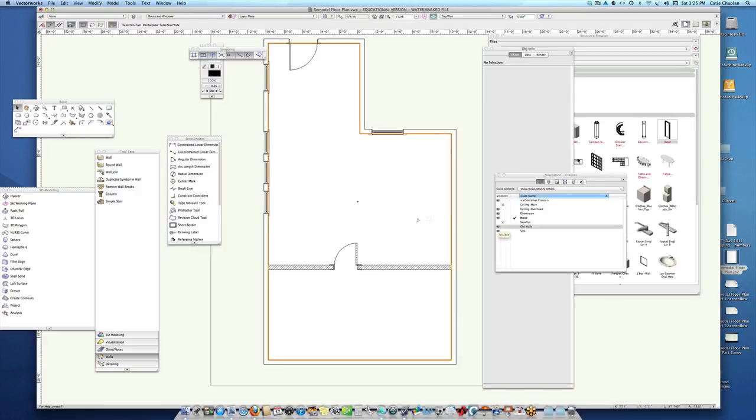And so I can have an existing floor plan with the old walls and a new floor plan with the new walls, and I don't have to keep jumping back and forth between layers. If I make one change, it gets changed in everything. I find this is a nice way to show existing and old or new. And when you create your viewport, you just select which walls you want to show in whatever particular viewport you're showing. So that's a nice way to use classes in your drawing.